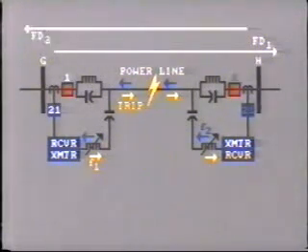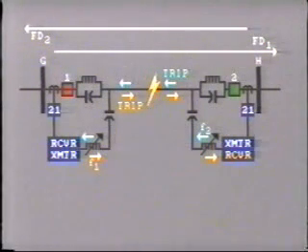This relay detects the fault and therefore operates to trip breaker number 2. At the same time, it keys the transmitter to key the unblocked signal to station G. This gives permission for the relay at this end to trip breaker number 1, so clearing the line.